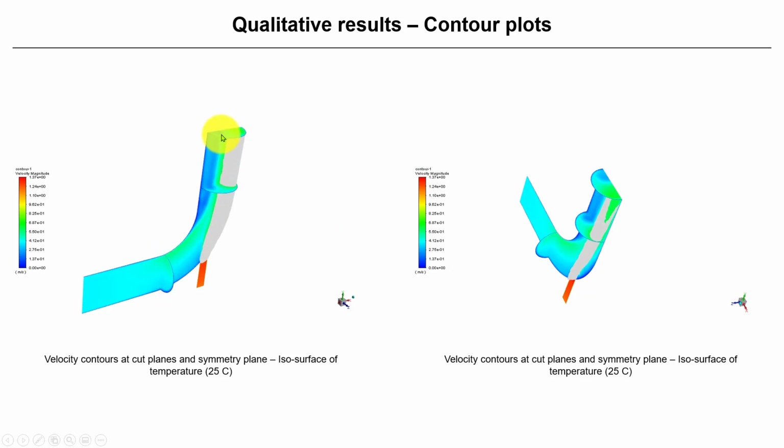So I will show you how to create the cut plane. It's pretty much the same as in 2D. You create a line, now you create a plane. Okay, so you choose the location, and see here that also we have isosurfaces where the temperature is 25. So it's difficult to see here. Well, later when we do the post-processing. The post-processing also is a little bit more time consuming in 3D. Now you can create these isosurfaces, cut planes, but the idea is pretty much the same.